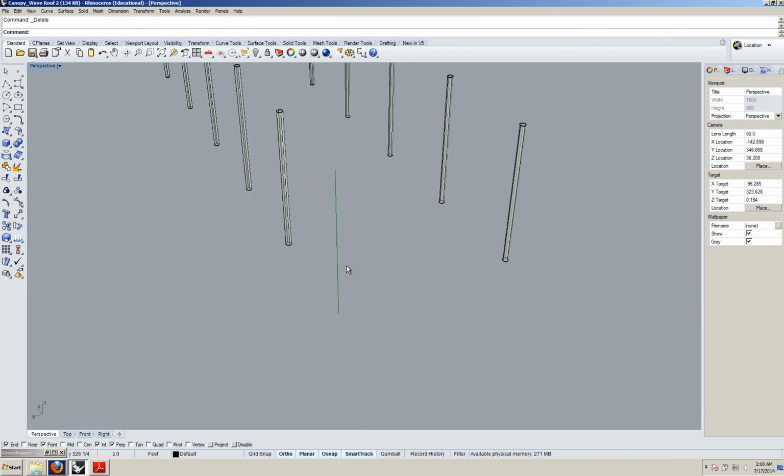If you did want to create a square tube or a square column, you could do that by making a square. Right? So you could use the rectangle command and start at the center. And so the center of the rectangle is going to be the end of the line. And then the dimensions are going to be 6 by 6. Oops, sorry, again, I am forgetting that this is in feet because I typically work in inches. So the center, and then 0.5 and 0.5.